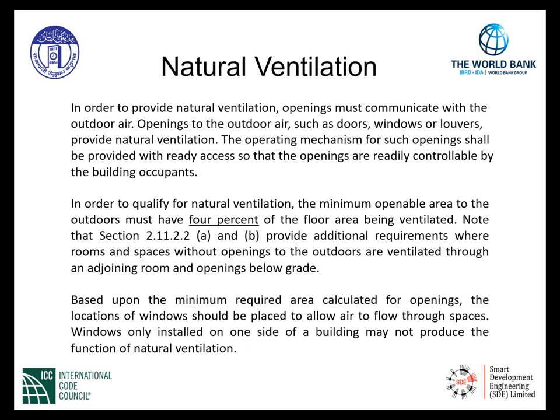In other words, we need openings to the exterior to draw in fresh air and properly ventilate the building. Not only draw in fresh air, but we hope that the air that's drawn into the building will somewhat disperse through the building and be exhausted out the same openings naturally.